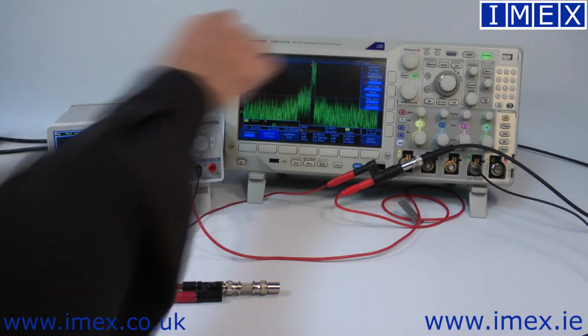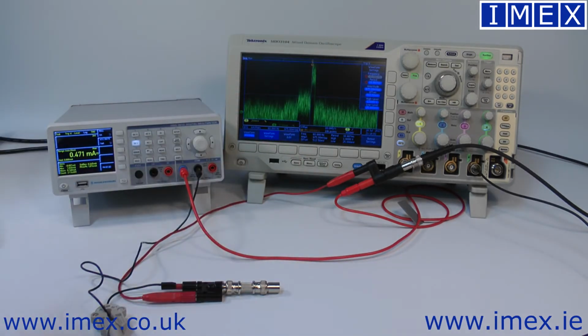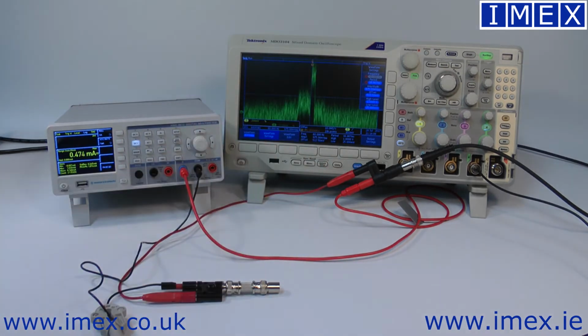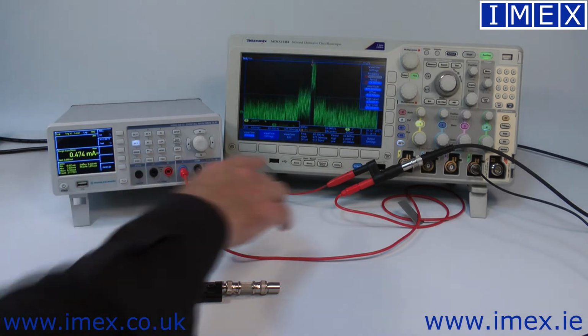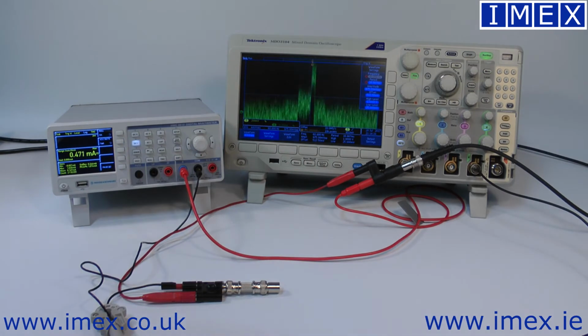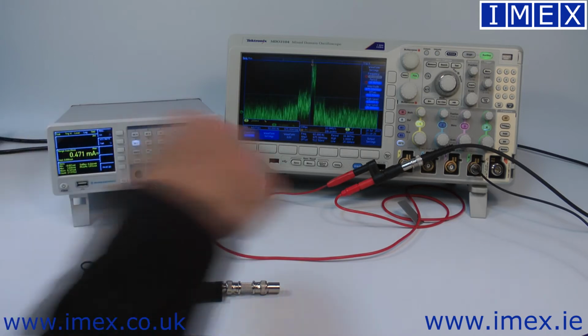It is giving us our 20 milliamp peak to peak. I'm on a 5 milliamp scale here. The probe itself is 1 milliamp per millivolt. So we're on a fairly low level setting on the scope, so we're seeing the noise. I've optimized this as best we can. I've set the bandwidth limit on the scope to 20 meg. I've set the bandwidth limit on the probe to 500 kilohertz. And yet we still have noise.